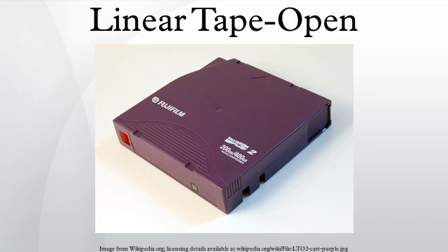Cartridge memory. Every LTO cartridge has a cartridge memory chip inside it. It is made up of 256 blocks of memory, where each block is 32 bytes, for a total of 8 KB. This memory can be read or written, one block at a time, via a non-contacting passive RF interface. This memory is used to identify tapes, to help drives discriminate between different generations of the technology, and to store tape use information. Every LTO drive has a cartridge memory reader in it. The non-contact interface has a range of 20 mm.